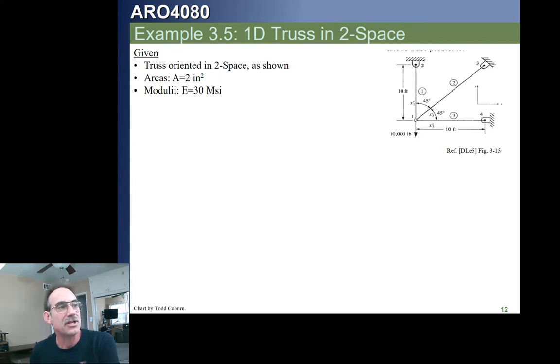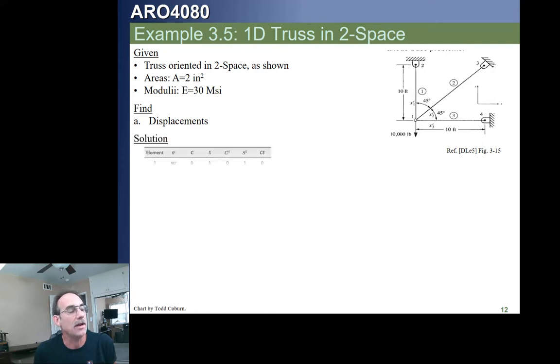We've got the modulus of elasticity of these, and we can see from the picture what the geometry is. Having said that, we're now ready to start moving with our method, which means we're going to start by looking at all the stiffness matrices, right? We want to find our displacements everywhere, which basically is at node 1. So we start by saying, okay, we've got 3 elements and we've got information about each of these elements.